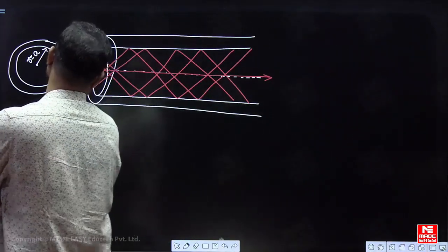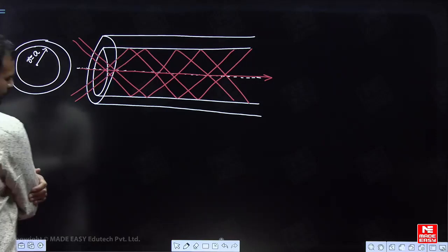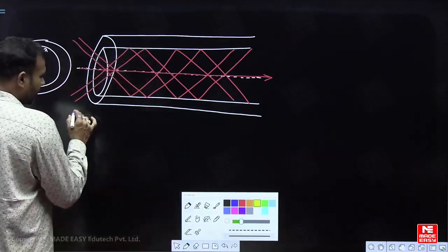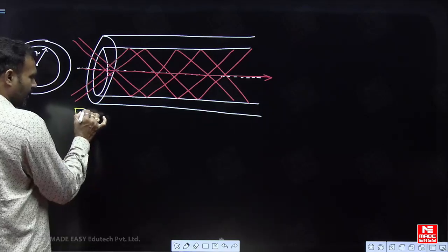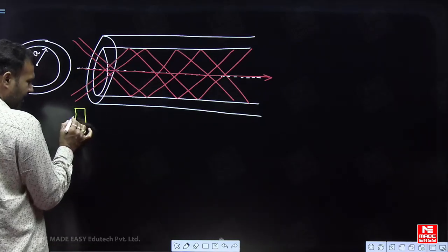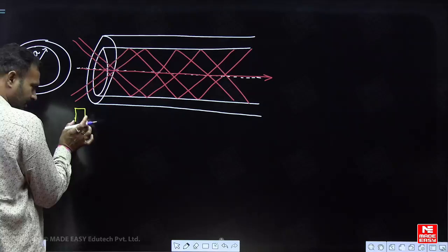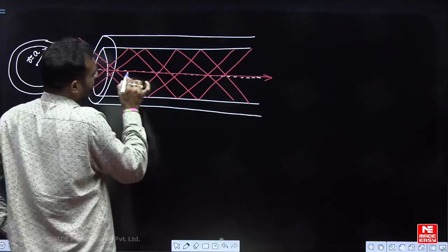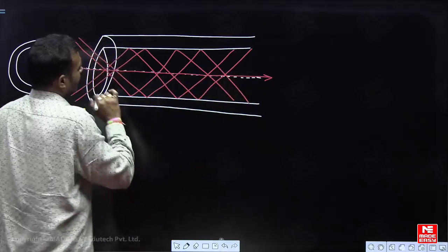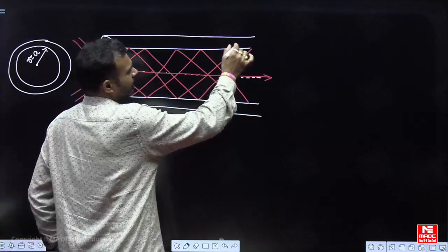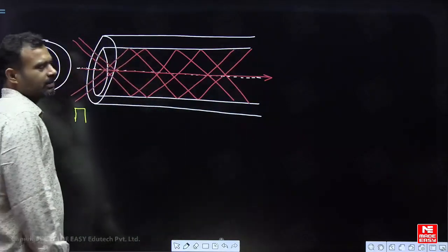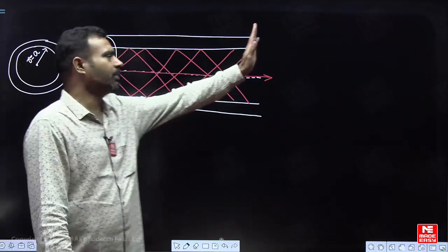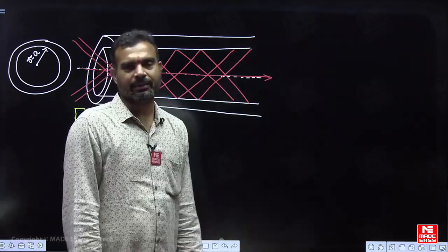This is the meridional rays we have. So, light is passing through the meridional rays. Next important point. I am giving a small pulse. The pulse has a number of light signals present. All these modes are present within this pulse of light. See, the center ray will move very fast and the remaining rays move slowly. Then there will definitely be a difference in the modes reaching the end of the fiber. Definitely, they will reach at different times.